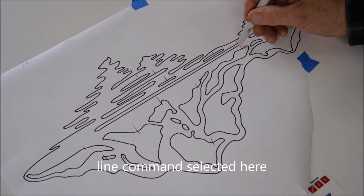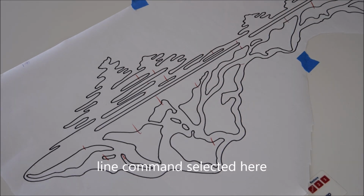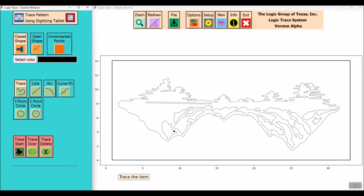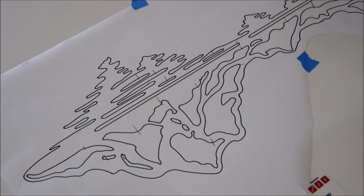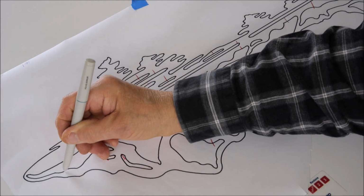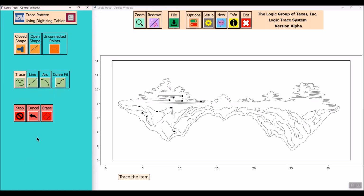This shows where I selected the line command. And you can see the line command is very quick. You're only selecting a few points and it creates the tracing. One unique feature is the ability of the program to extend the control window to another device like a cell phone or an iPad. This way you can make your selections right beside you, real close to where you're tracing. The control window is the window on the left-hand side where you're making all your selections with those buttons, the line, tracing, curve fit, or arc.